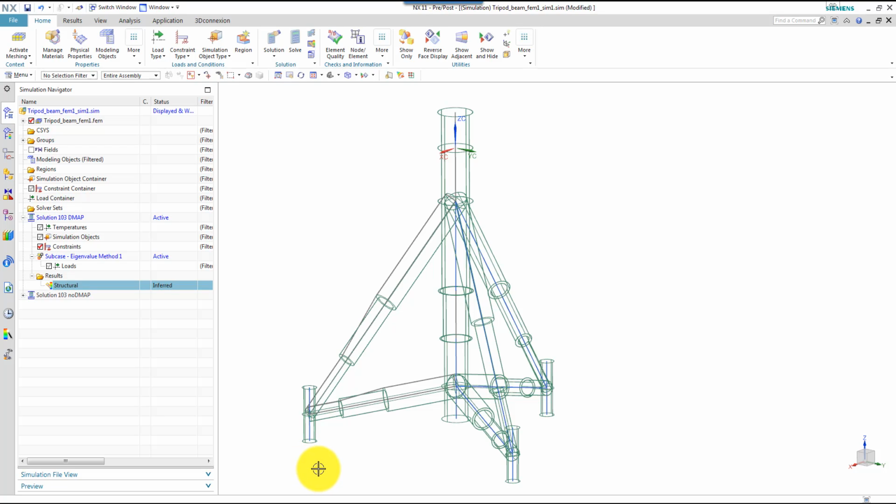I will define an ASET which corresponds to the triads. And in my ASET, I will put this node, and this node. Those are 3 nodes I will fix to the seabed. And in addition, I will keep the lower node here in the tower and the upper node as external as well. That means I will have a total of 5 external nodes in my super element.